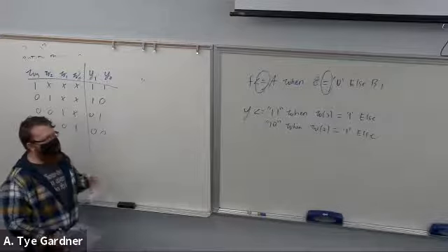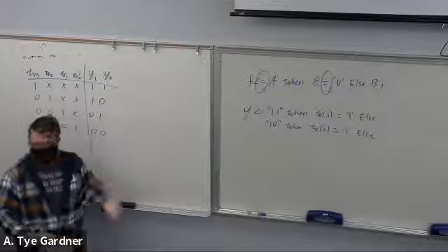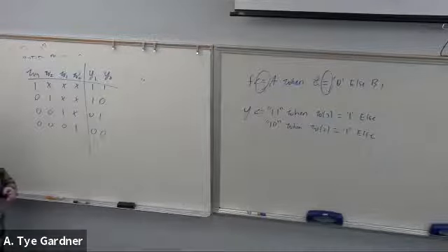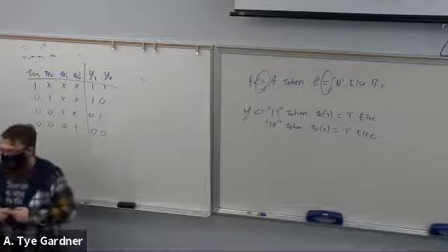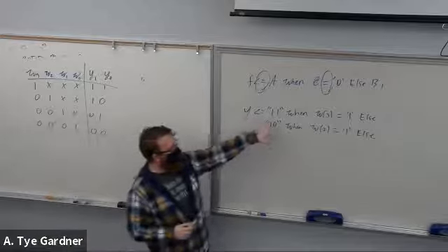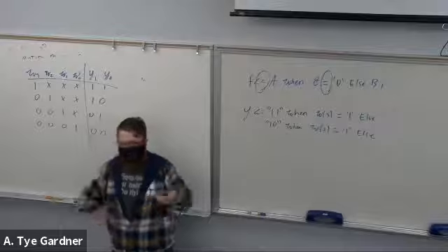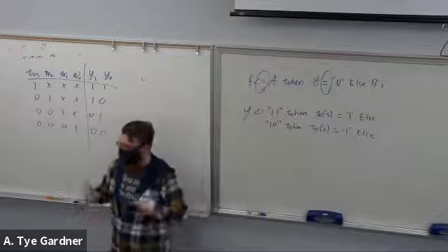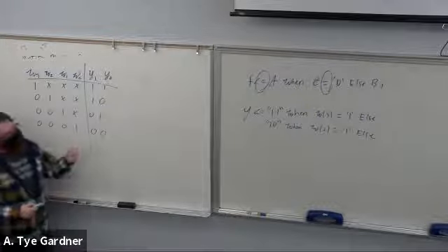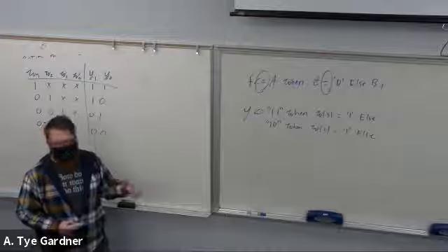I don't have to worry about every line. I don't have to write all of the equations. I just say, in order, this is what I care about. Now, you'll see that same kind of logic being written in all sorts of circuits, right? Where your first line will say something like when enable equals 1, right? So if enable doesn't equal 1, just stop. We don't want to do any computation if we're not on, so just stop. So this kind of ordered conditional assignment can be very useful to simplify logic.